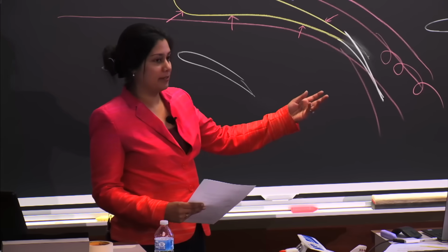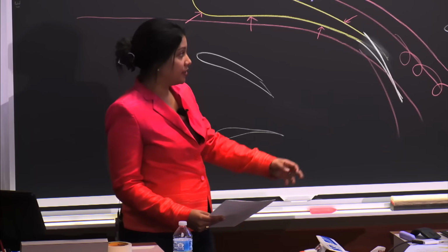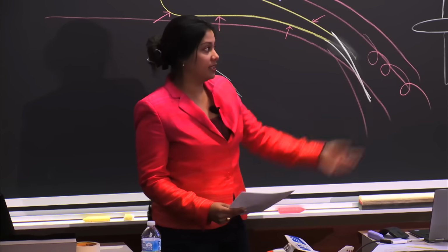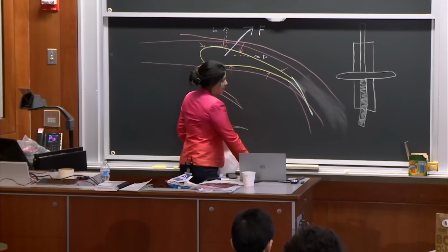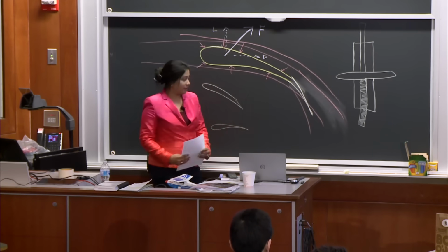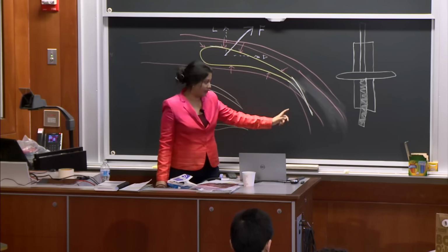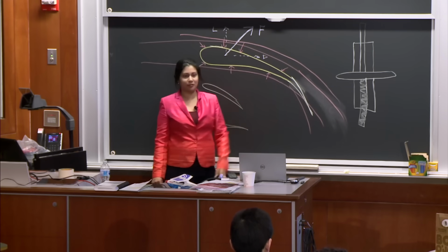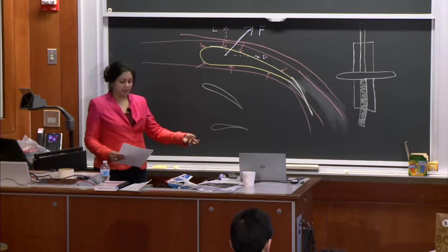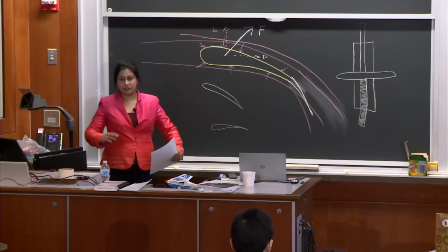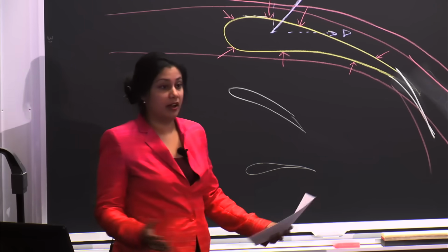And we impose some limitations or conditions on the airflow, which are not actually true, but help us with approximating lift. One of those is the Kutta condition that you see at the bottom left, which is this smooth flow off. Basically you say that none of this turbulence is happening, and the air moves very cleanly off. You also have a couple other specific requirements, such as that no air molecule from the top comes over to the bottom, and no air molecule from the bottom goes around to the top. You just assume that they move smoothly off. So that Kutta condition is actually very helpful in approximating lift. We also make other assumptions that there's no viscosity or that the fluid is not compressible. Sometimes these assumptions are appropriate and sometimes they're not.